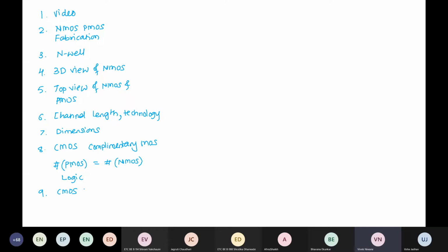Next, CMOS always provides complemented output. मतलब क्या? हमेशा inverted output रहेगा उसका. Okay, so whenever we are going to implement our design, first design is inverter. Okay, it says that Y is equal to A bar. Next design is NAND. Its output equation is (AB) bar. Next design is NOR. Its output equation is (A plus B) bar. Okay.